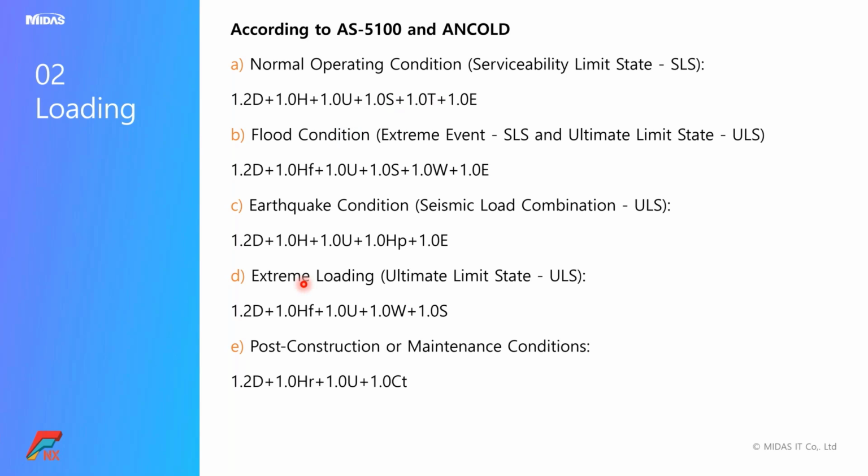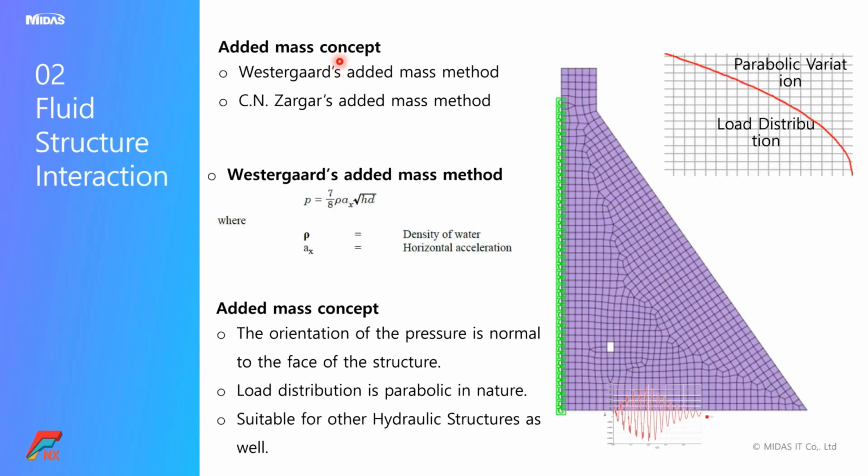So I will just show you the load combinations once during the application of the fluid structure interaction. So the next concept is the fluid structure interaction. Let's say we have a dam and we are considering the reservoir. There are two ways to consider the reservoir. One is to apply the entire reservoir as a mass, and the other is to create the reservoir completely.